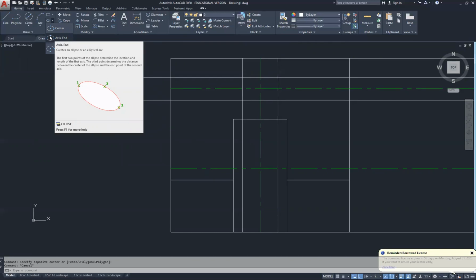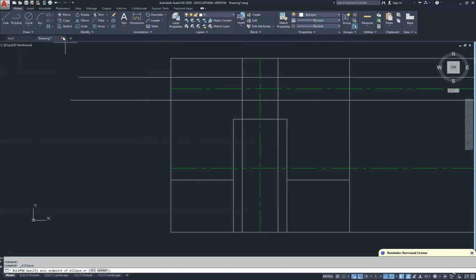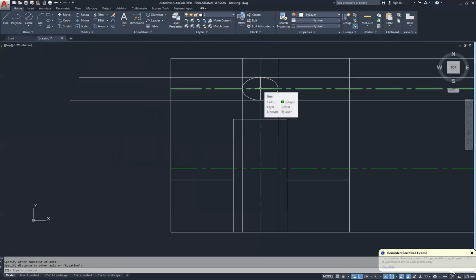All right, let's go ahead and demonstrate that by using the command. I'm going to use the intersection along the center line and the other side. And then I'm going to move my mouse up and select the intersection at the top. And the bottom is made automatically. So this is what that circle looks like on a foreshortened view. Now, this is just the entrance of the hole that's going through the piece.